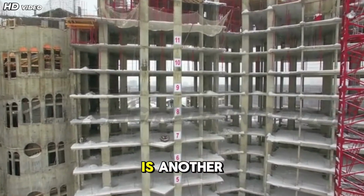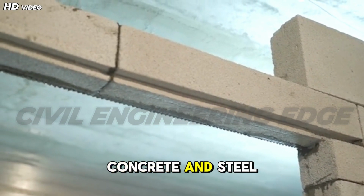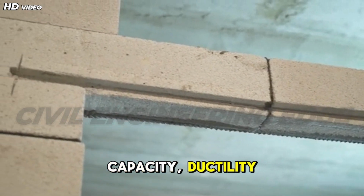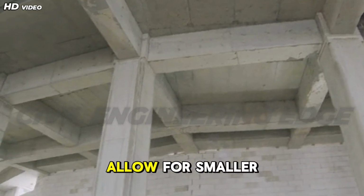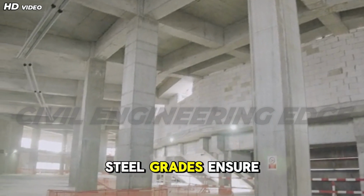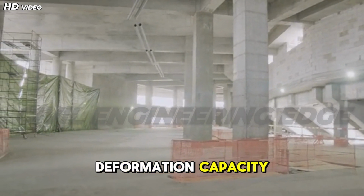Material selection is another important component. The grade of concrete and steel directly affects the load-carrying capacity, ductility, and durability of the column. Higher grades of concrete allow for smaller cross-sections, while appropriate steel grades ensure adequate tensile strength and deformation capacity.